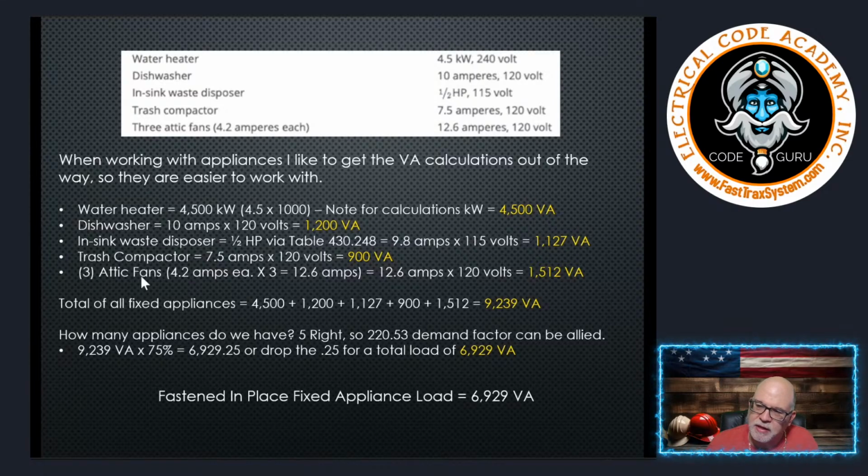And then we have those three attic fans. Might as well bulk them up, a summation of them, add them all up together, which is 12.6, which is 4.2 times 3, in case you wonder where I got that. Same thing here. They're all listed as 120 volt in our exam question. So we're going to do these at 12.6, sorry about that tap in there, times 120, remembering to use what they gave us, and that is 1,512. So we have all of them.